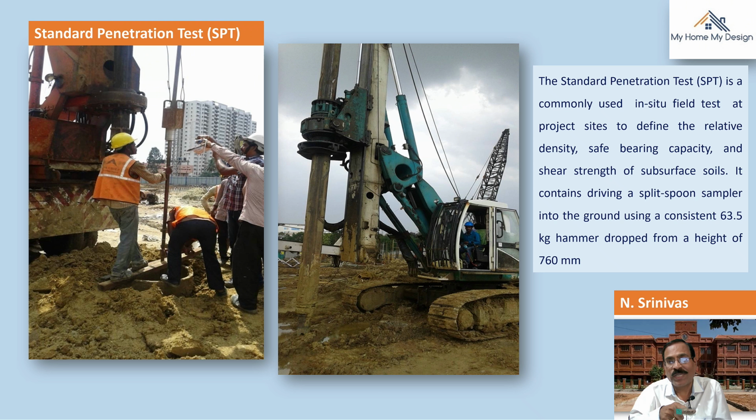For pile foundations, the standard penetration test is absolutely required. The standard penetration test, SPT, is a commonly used in-situ field test at project sites to define the relative density, safe bearing capacity, and shear strength of subsurface soils. It involves driving a split spoon sampler into the ground using a consistent 63.5 kg hammer dropped from a height of 760 mm. This soil exploration test can be used for pile foundations and also for normal foundations.